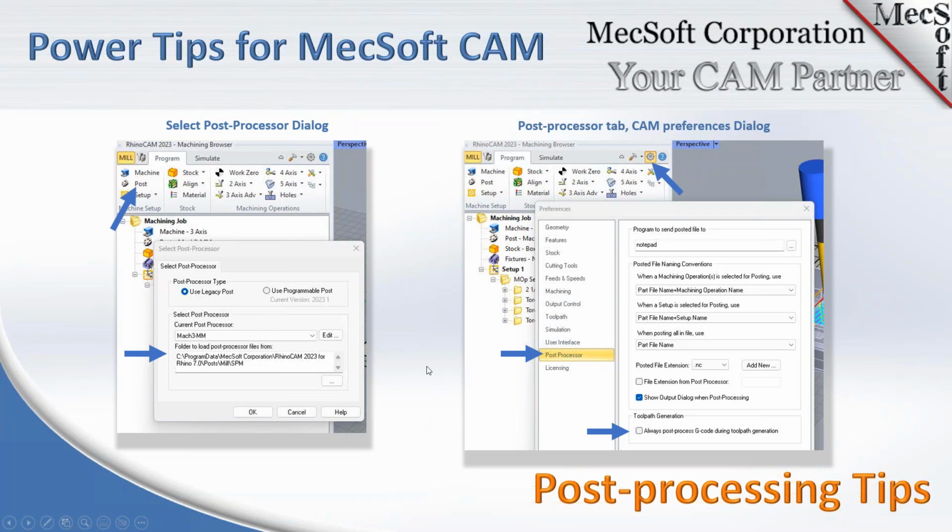Okay, we have two slides here for post-processing tips. A lot of users, if you're new, may run into cases where all of a sudden your post processor is no longer listed in your select post dialog, or it's not listed up here under the machining job. You're not sure where it went or why it did that. We're going to tell you how to fix that and how to make it so it won't disappear again. We're also going to look at the post-processor tab on the CAM preferences dialog. We'll show you that and talk about some of these when we do the demo.